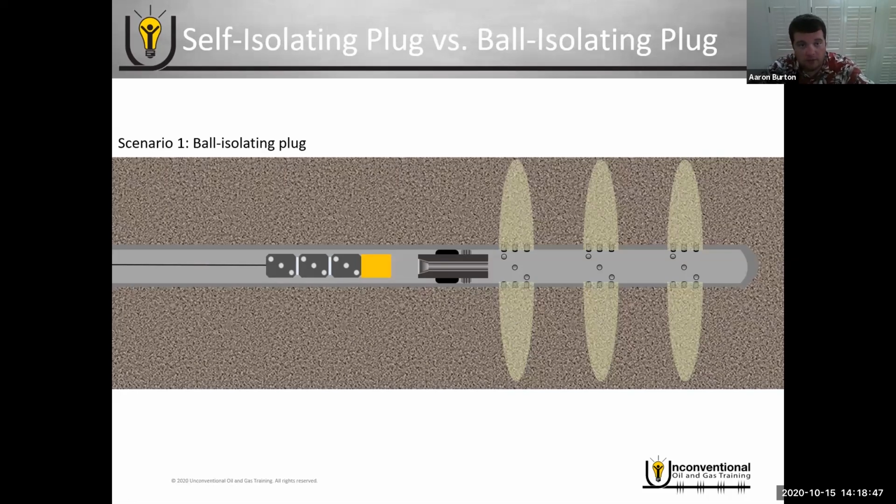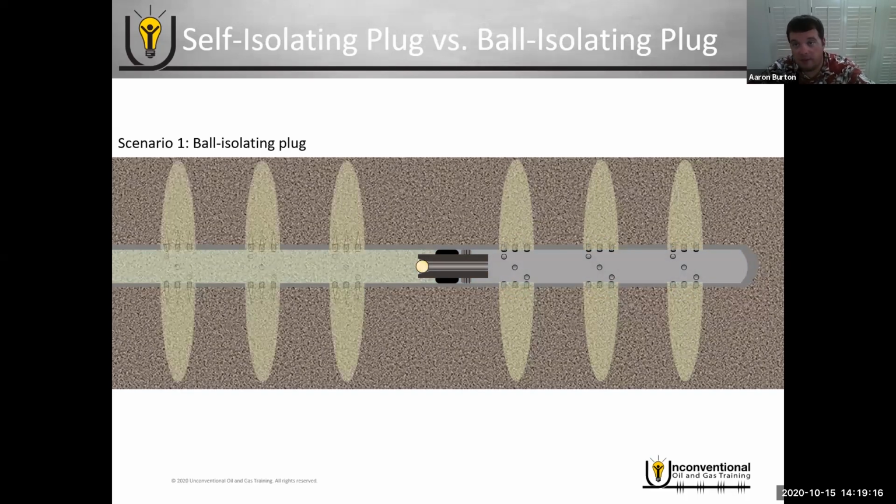So we send our electric signals, fire all of our clusters of perforations, and once we've done that, pull out of hole with the wireline. Now, as you start pumping for the second stage, you're going to lead in by dropping a frac ball. As you continue pumping, the ball will go down hole, land on seat, isolate from the previously fractured stage, and force the fluid to divert out of the second stage perforations.